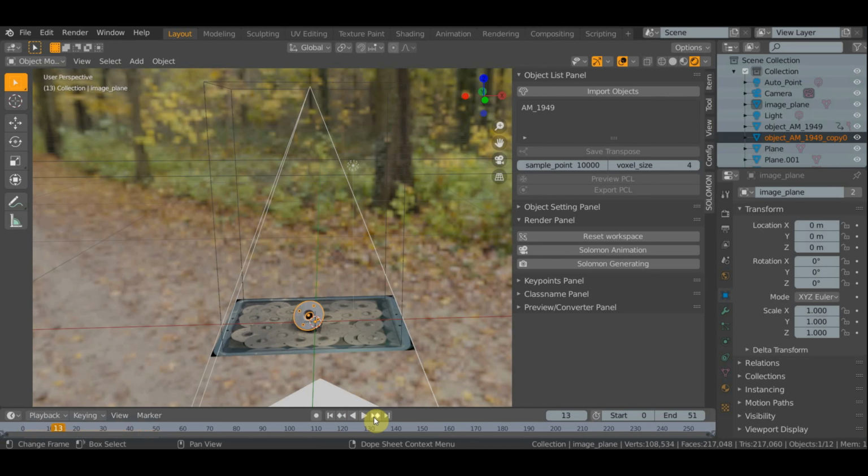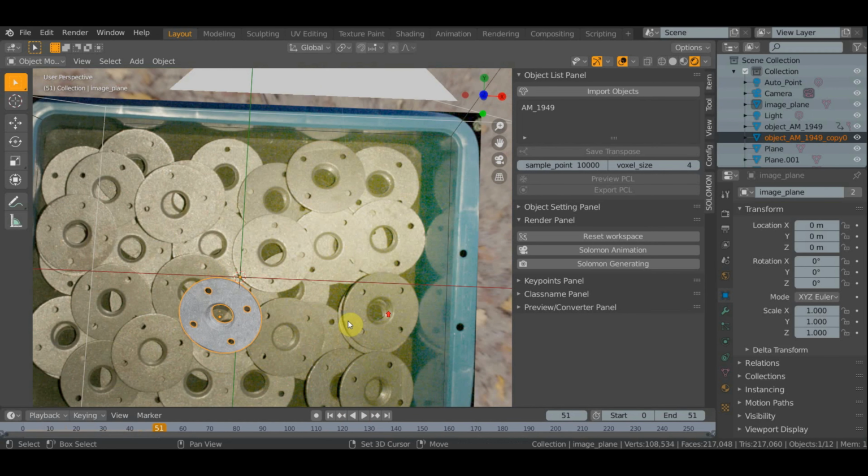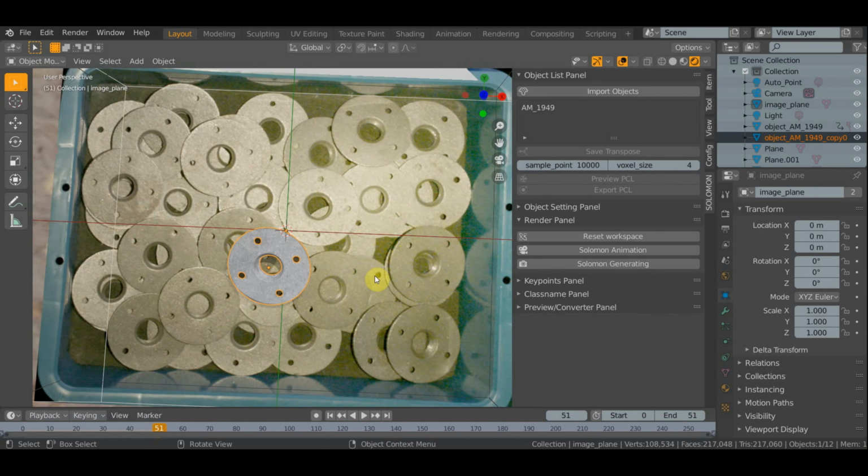In the Config tab, we left 50 frames as default to capture every image. For the majority of cases, 50 frames should be enough to have all the objects well placed close to the background image. You can modify this value, but the bigger the frames of the video, the higher the computational time will be. You can stop the video at any time. It won't affect the moment when the auto-labeling tool will capture the image, because it is predefined to be at the last frame.